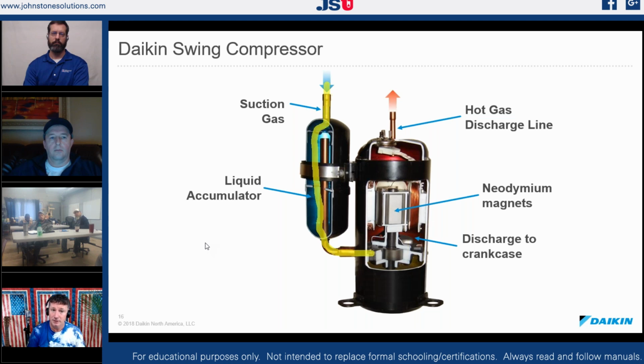And we went, wow. So we contacted our manufacturers and we got back to looking at installation manuals. They went, I guess we didn't look at that very well. Like, I don't think you did. So if you look at all of our new installation manuals for rotary compressor equipment, every one of the installation manuals now says, at least our manufacturers, open that liquid line first, because of this right here. So be aware, if you have a rotary compressor of any brand, any piece of equipment on an installation, make sure you're opening that liquid line first and not that suction line.